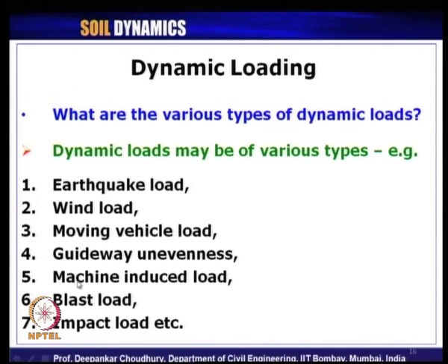Then another type of dynamic load is machine induced load. When any machine is running or moving, the rotating component of the machine or the applied loading on the machine, because of those movements, can induce dynamic load. Then of course, blast load is another type of dynamic load, because here also the load varies with respect to time. Impact load is another example of dynamic load.